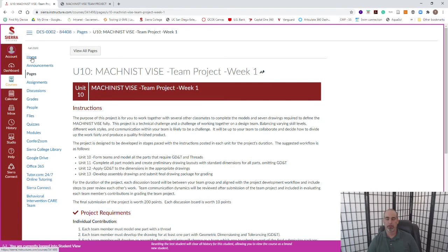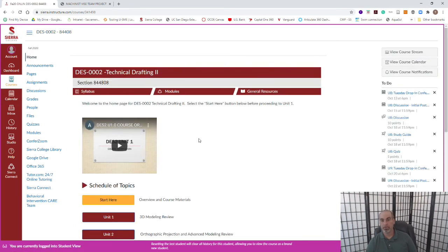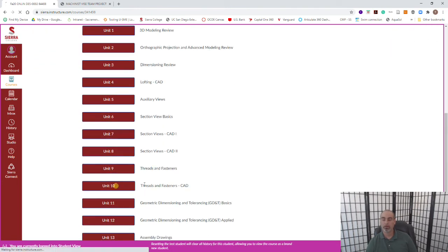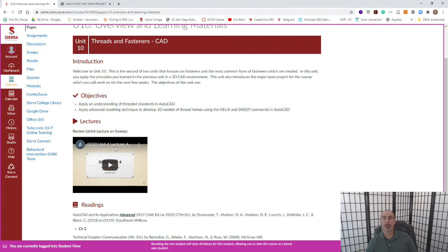Again, email me with any questions. The lecture materials for the unit will be embedded in the project, but I also have a review of one of the lectures from Unit 4, which is on sweeps. The procedure to make a thread is to first make a helix, and then you use the sweep command. So you might want to review that lecture, and the balance of the lecture will be embedded in the project.